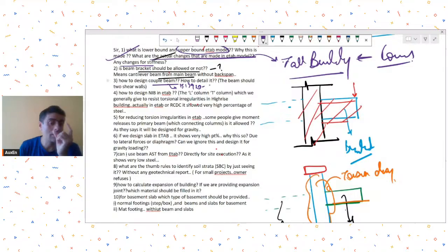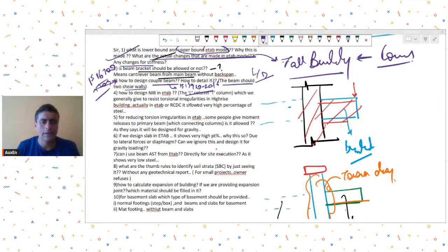Okay. Details of coupling beam design are given over there. Mainly how to provide diagonal reinforcement, when to provide diagonal reinforcement. Those provisions are given over there. So you could refer to the coupling beam design. Additionally, you could refer to IS 16700 provisions. The design is nothing different, just that you have to introduce diagonal reinforcement for certain L over D ratios. So you could refer. Then in our tall buildings course, we have dealt with the coupling beam design also in quite a lot of detail.